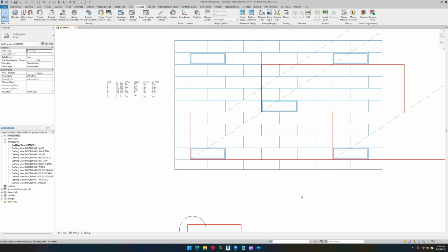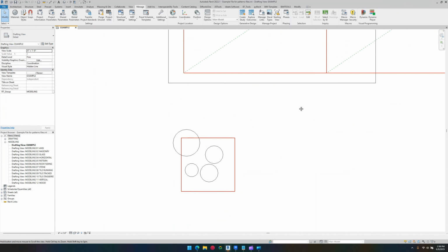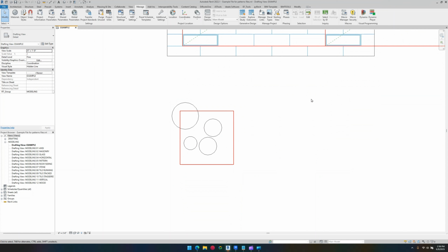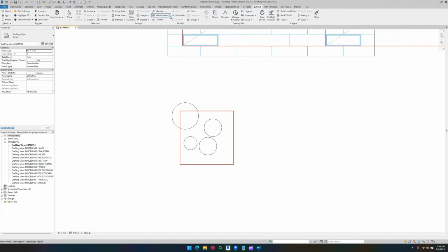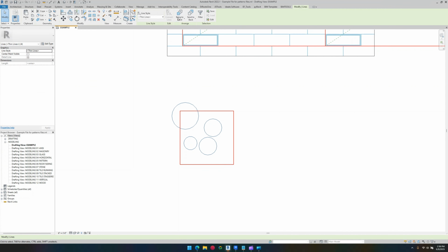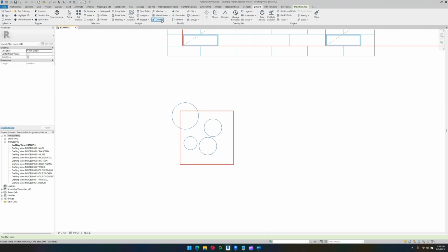One of the other methods I use when I am creating patterns, and that people talk about, is to use pyRevit. And pyRevit is a very powerful tool that makes it really easy to make patterns. So simply all you need to do is highlight and then go over to pyRevit and click Make Pattern.